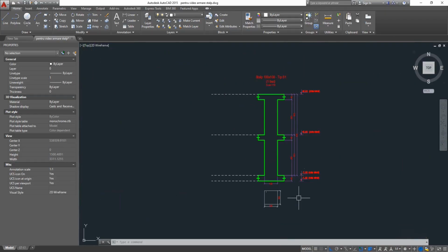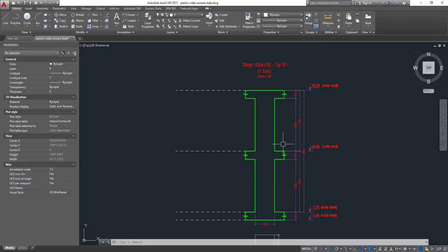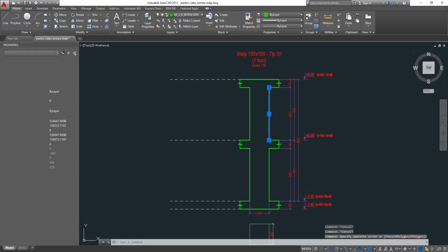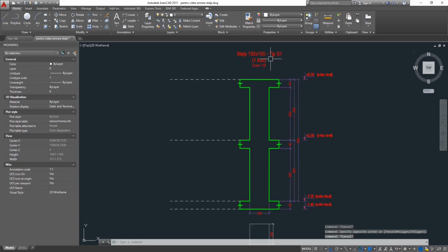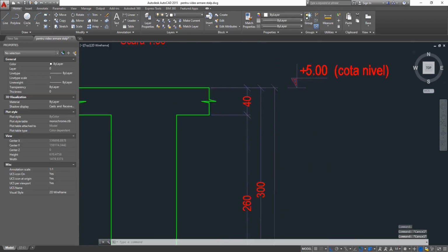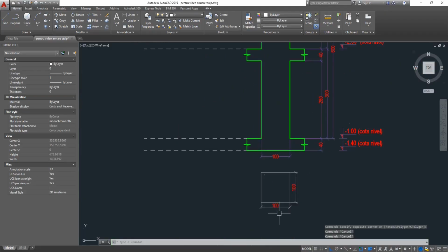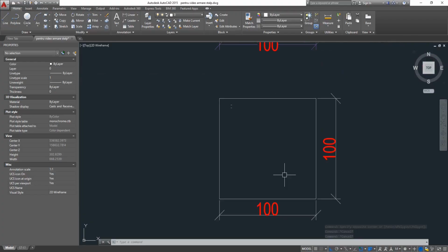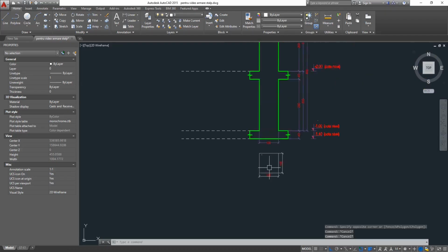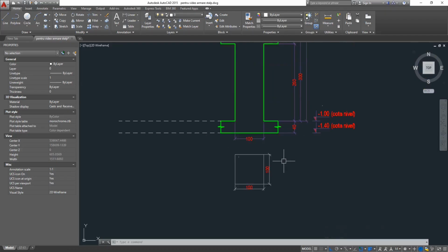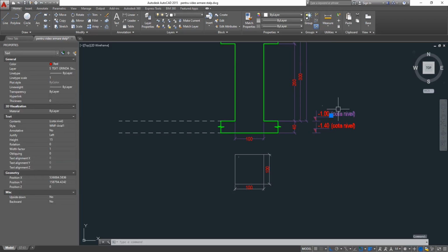To simplify things, we shall build a two-level column. What I have here is a basic drawing in AutoCAD, comprising lines, dimensions, some texts, maybe some symbols like the level one, and some special lines dedicated to a special layer, which will have the name of guiding lines, let's say. It's meant to help the dynamic block and transmit the data via fields to various objects like the text. You will see.